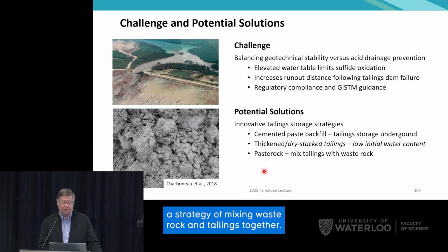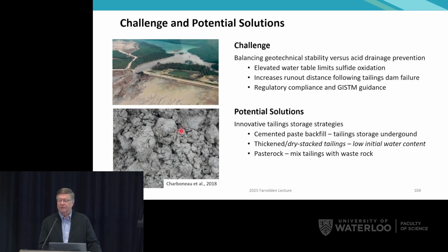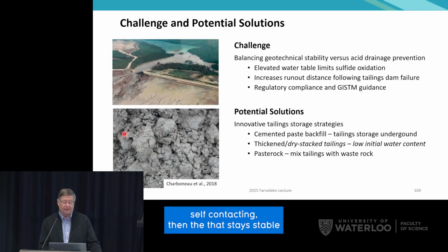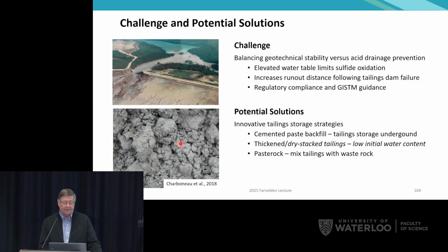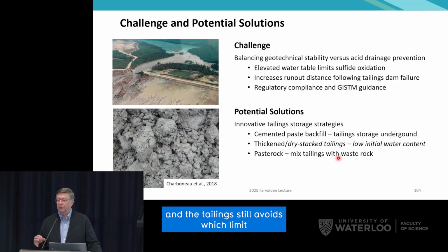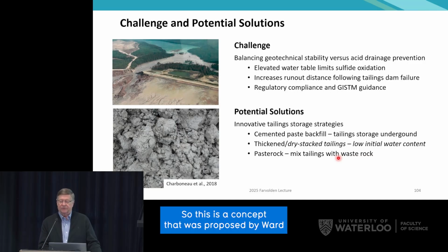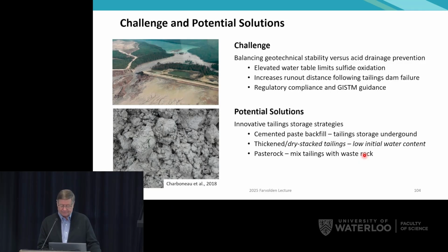And then there's a strategy of mixing waste rock and tailings together. So this is paste rock, which is a mixture of tailings and waste rock, which, if the waste rock is self-contacting, then stays stable. And the tailings fill the voids, which limits the advective gas transport through the rock. This is a concept that was proposed by Ward Wilson from the University of Alberta two decades ago and has really gained popularity in the last 2 to 5 years.